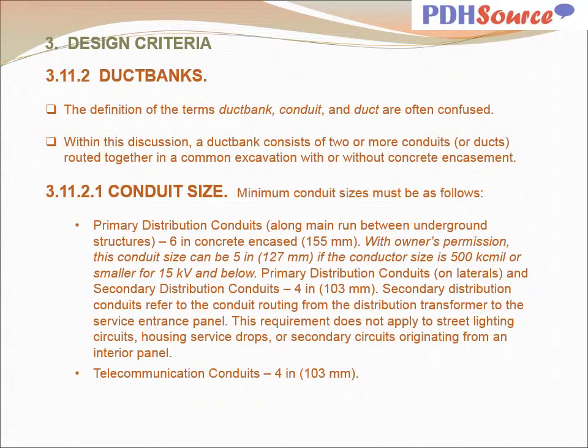The definition of the terms duct bank, conduit, and duct are often confused. Within this discussion, a duct bank consists of two or more conduits or ducts routed together in a common excavation with or without concrete encasement. Minimum conduit sizes must be as follows.